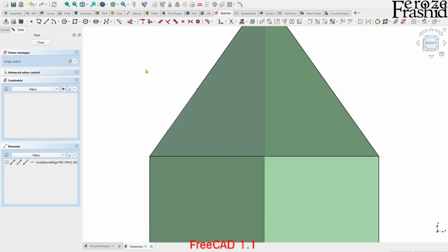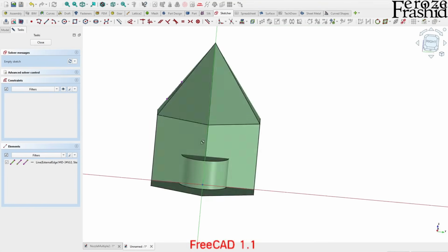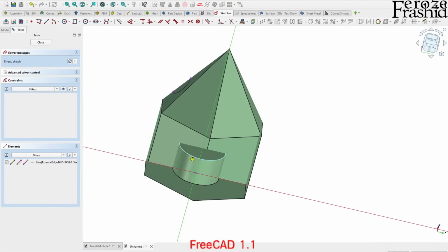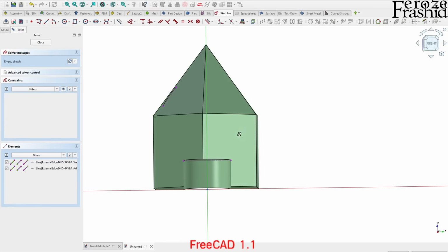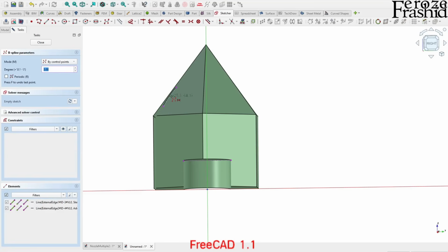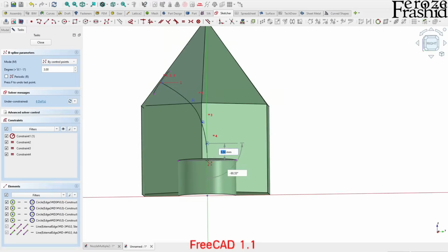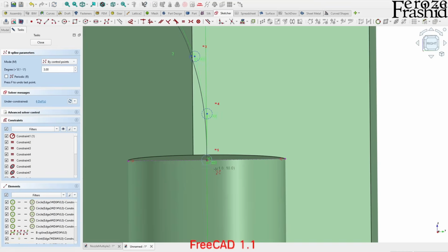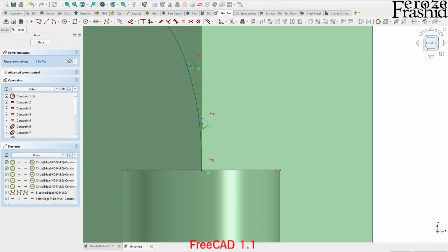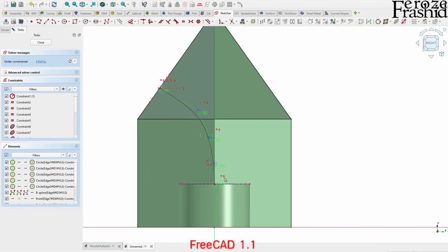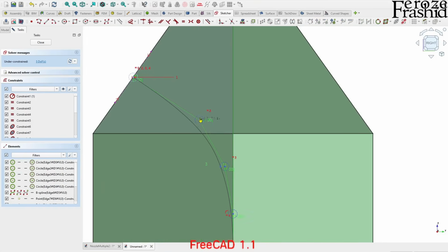And now I can have an edge. Actually, let's take this one too. So the external geometry, we just brought it in. Now I can take a B-spline and kind of go from the center at somewhere here. I want to come in the middle there. Okay, so I want to place this first intermediate point after the start on this axis, so that is a tangential end. And I want to place this point.